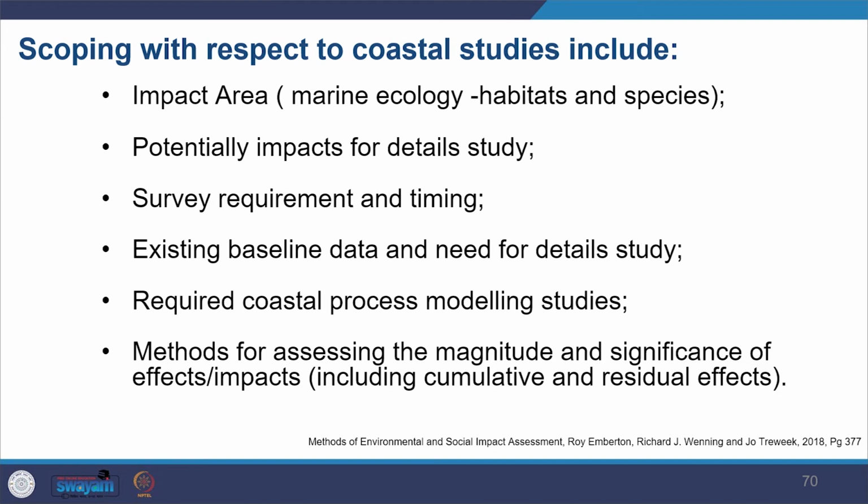And then you would look not only at the area, but also at the impacts, what potentially significant impacts would happen, and because of that, what indications you are getting in the scoping stage, so that you might have to take up a later detailed study with respect to that. And then at the scoping stage, you would also decide the time of survey, like when you're going to undertake this survey, depending on what kind of impact would be there and what kind of area you have to cover. So you also need to decide the time of survey, in which season you would do it, and what frequency you would do it at.